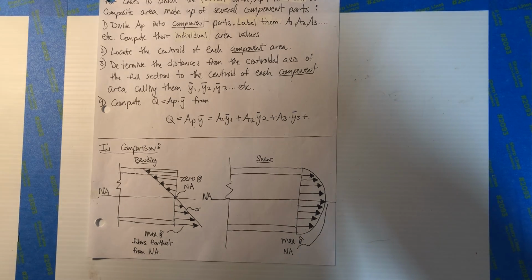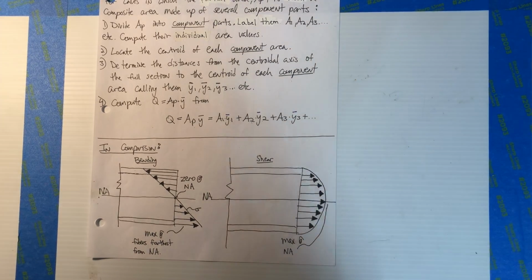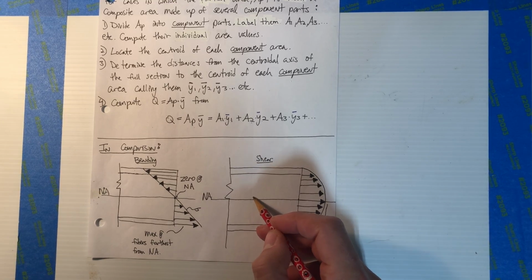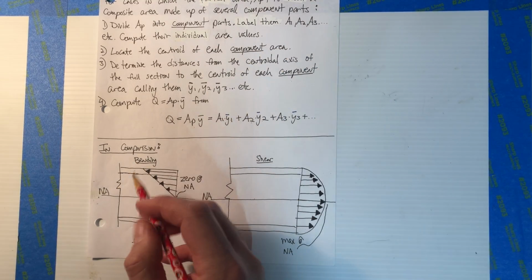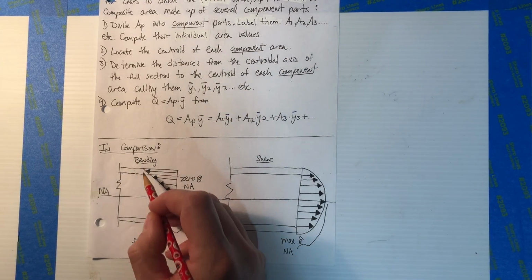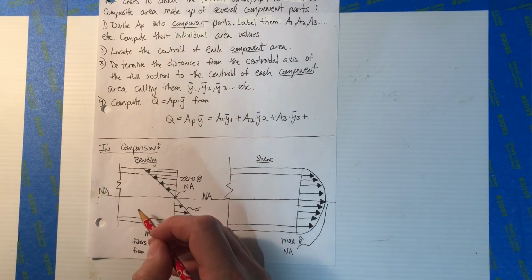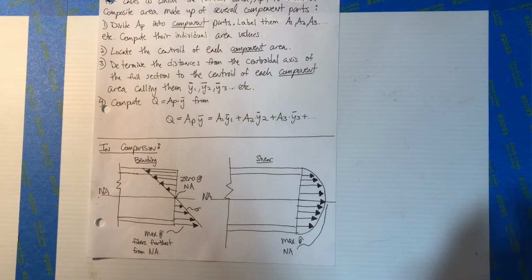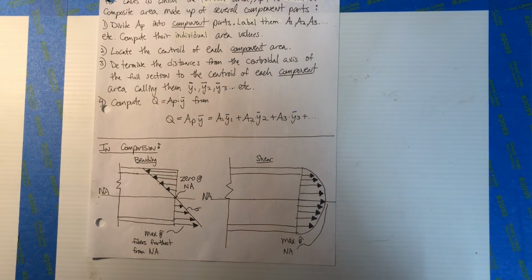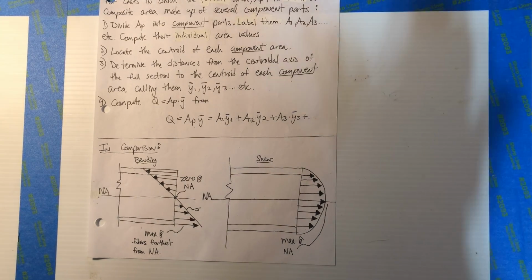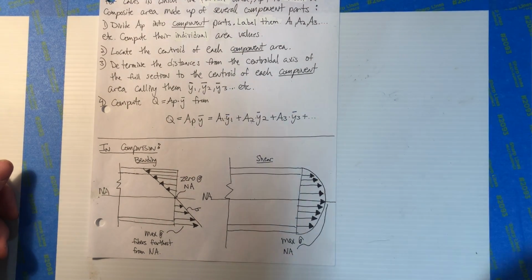There may be a point of interest somewhere else in the beam's cross section, maybe where the flange and the web meet. But predominantly the max shear stress is going to be found here, and the maximum bending stress is found depending on which way the beam is bent, compression or tension, but the values should be similar, okay? That's the end of the background theory. The next couple of videos, 2 or 3, will be on examples.